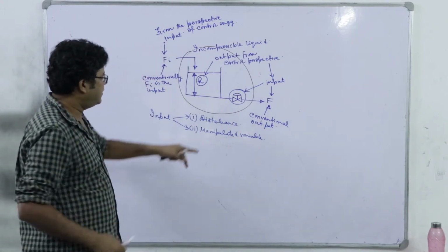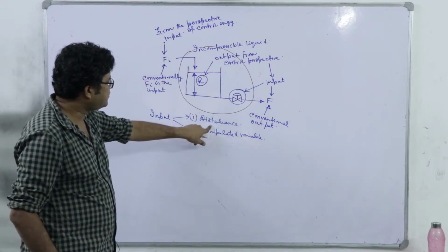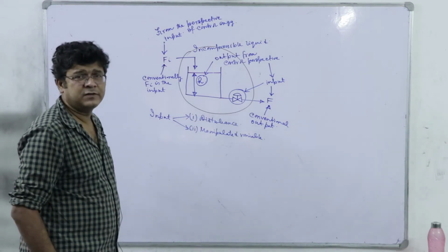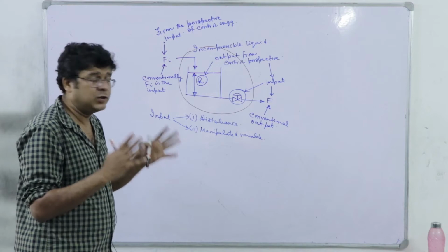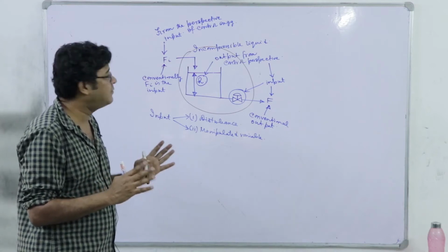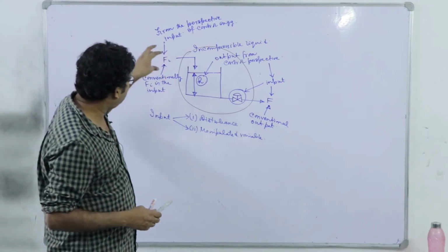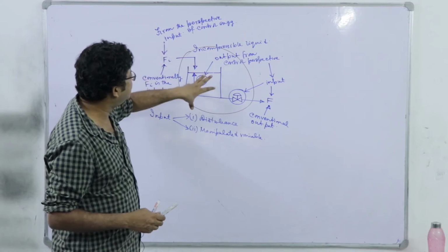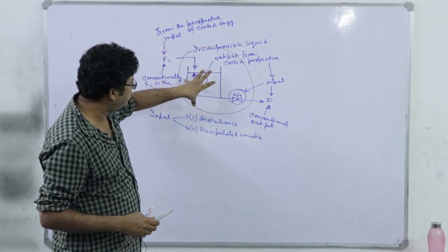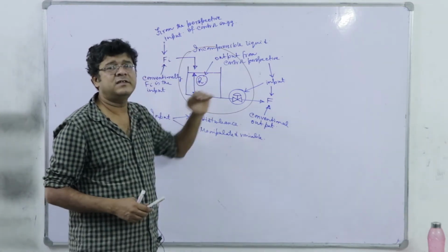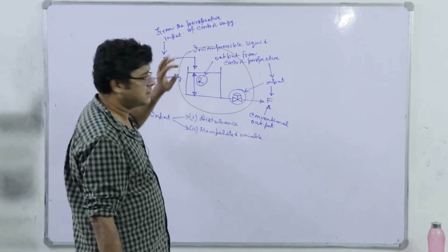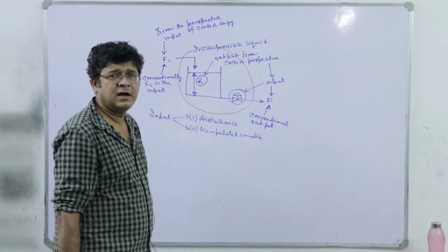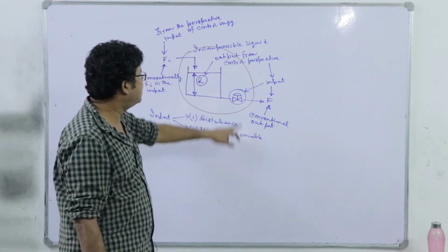So disturbance, you see, is something over which we are not having any control, and that's why we need to control this device. This is a source which will deviate the system from its desired steady state. Say the system is operating in the steady state, Fi has got some value, say it is 50 liter per minute, right?